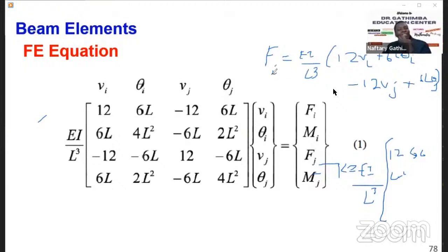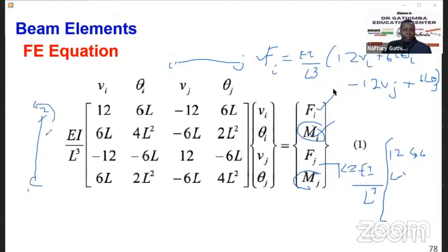So these were the slope deflection equations. So you can extract the formulas that you can use at the element scale, at the local coordinate scale. For the beam, you can get the shear force and the moment. So what we need to calculate the nodal forces, our nodal moment, is to extract the equation for Mi and Mj. Remember, we have i, j. And for our case, we have 1, 2. So we need to get what are the moments here, M1, M2. So we need to extract this equation.